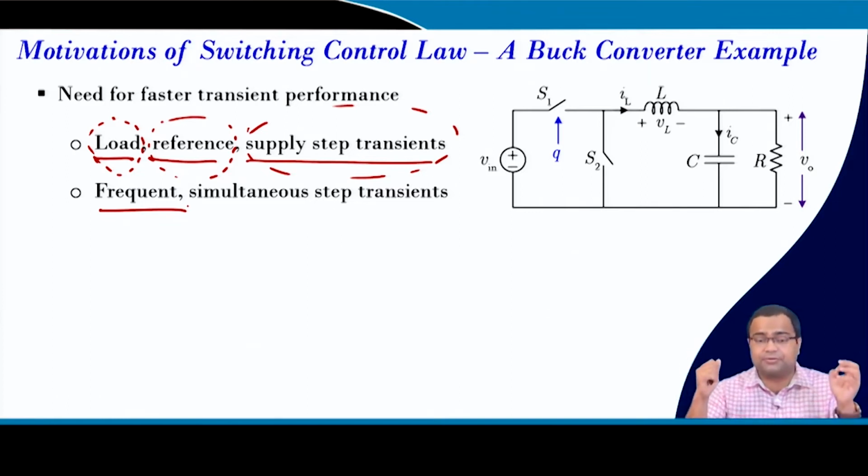Even for feasibility, to check whether the converter will sustain or not, they can go very close to the switching frequency just to check whether the converter survives or not. But the converter cannot respond beyond a certain frequency of the load transient, and control will play a significant role in how fast a load transient we can cope with using the converter.